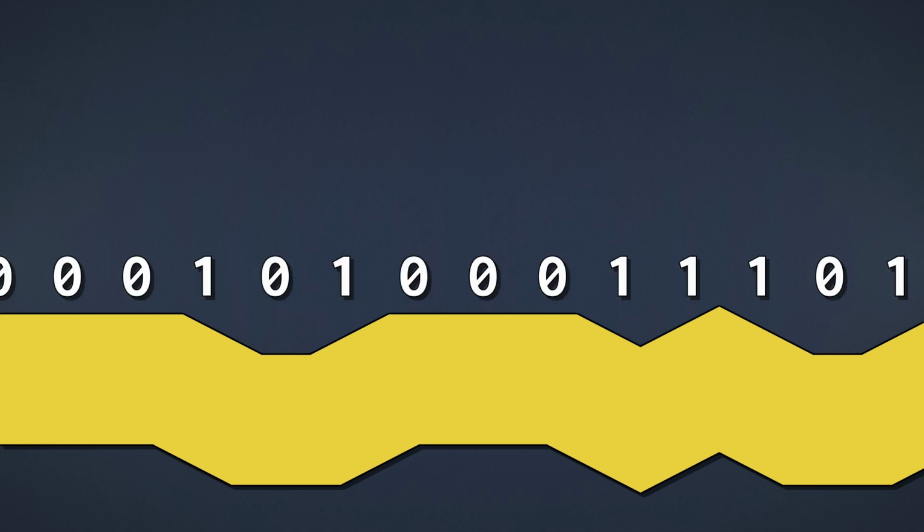Anyway, as with the hard disk drive, non-return to zero inverted, or NRZI, is used to represent our bits. Again, this means pits and lands don't represent zeros and ones. Instead, the transition between them represents a 1, while no transition represents a 0. You may be asking, where do these pits come from? Now for a CD-ROM, these are actually etched into the CD during manufacture, which is why it's ROM, read-only memory.